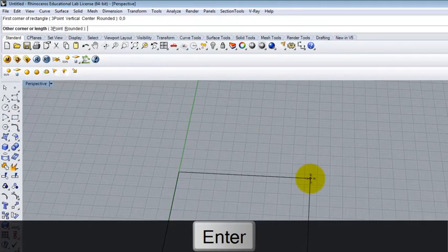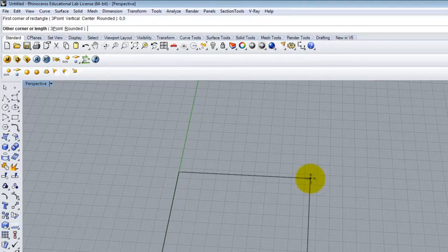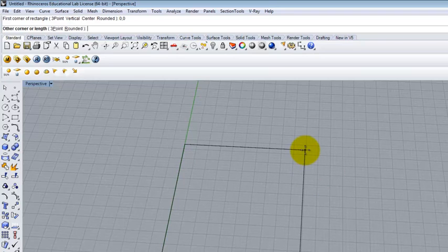I'm doing this in its own file because a pillow is the kind of thing where ultimately you're probably going to want to bring it in and use it elsewhere. If you're creating a pillow that's specific for your chair, where it needs to start a certain size or already starts with a certain shape, get that curve from your chair and then bring it in. You can just copy and paste it into a new Rhino file to work with it and then bring it back. So anyway, I'm going to do a pillow.